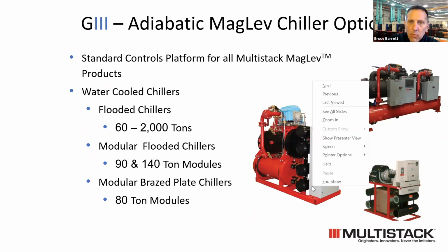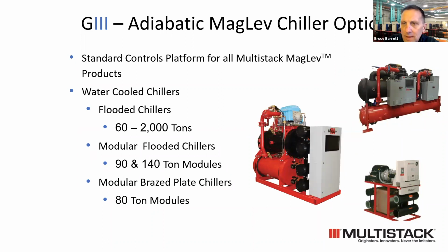All of these options in the water-cooled format can be done with adiabatic or split chillers. Even the modular machine can be done as a split chiller. So you can have a compact design in your mechanical room. You don't need to go to a larger flooded machine.